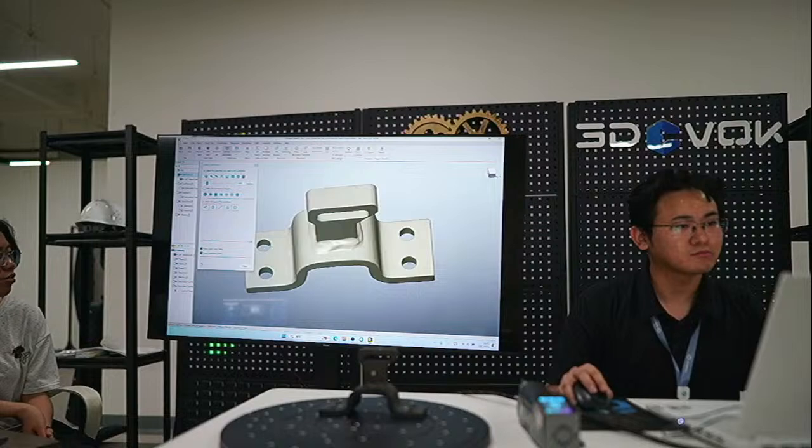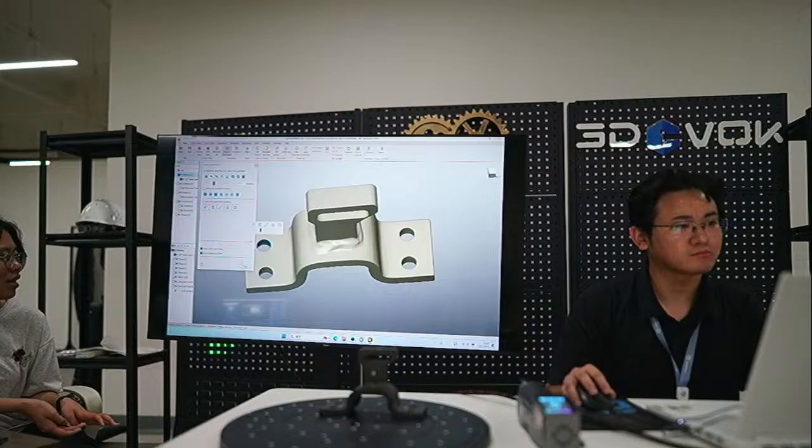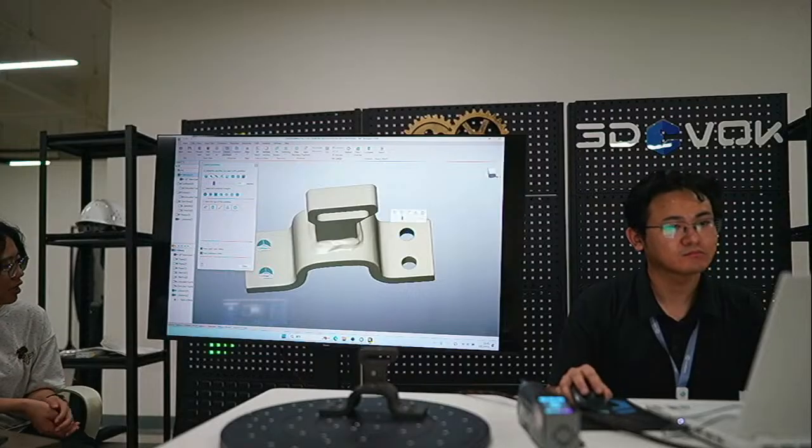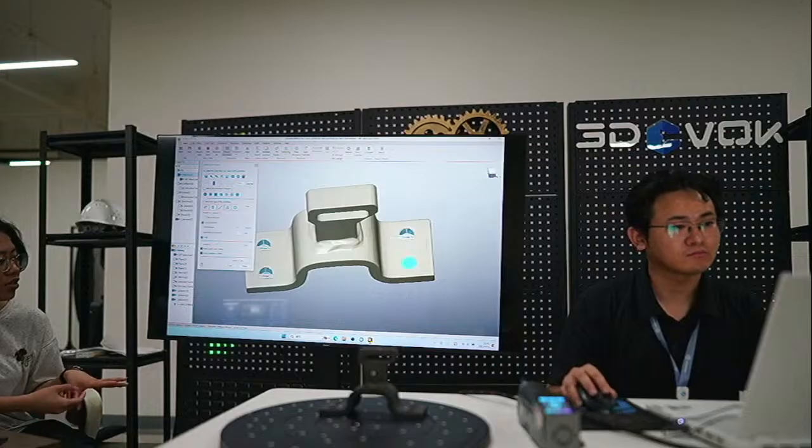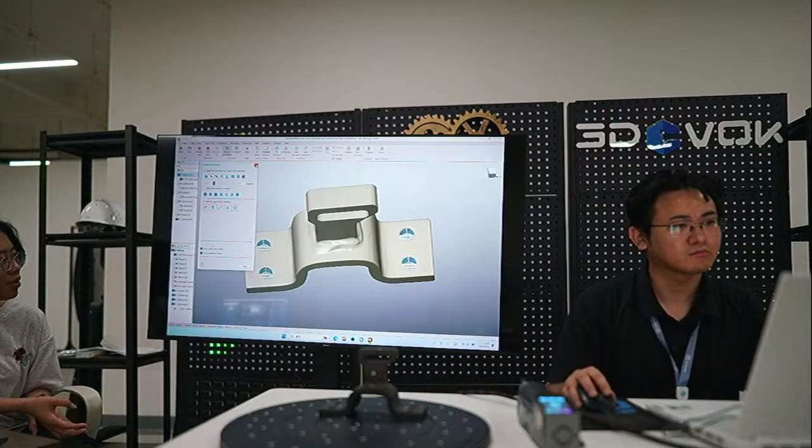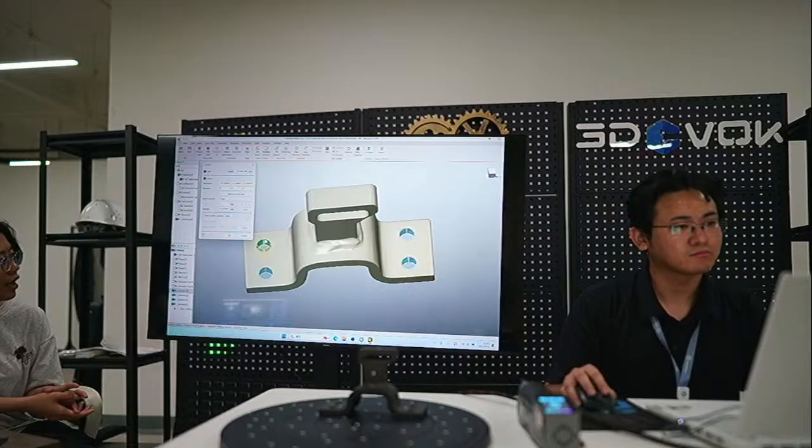Oh, right, we still need to dig holes. So we observe there are 4 holes on the industrial part. In this case, we need to create 4 cylinders so that we can dig the holes and remove the solids on the bottom part. To do the cut function, we need to extend the cylinder beyond its actual surface, so that we can remove all the unnecessary part.